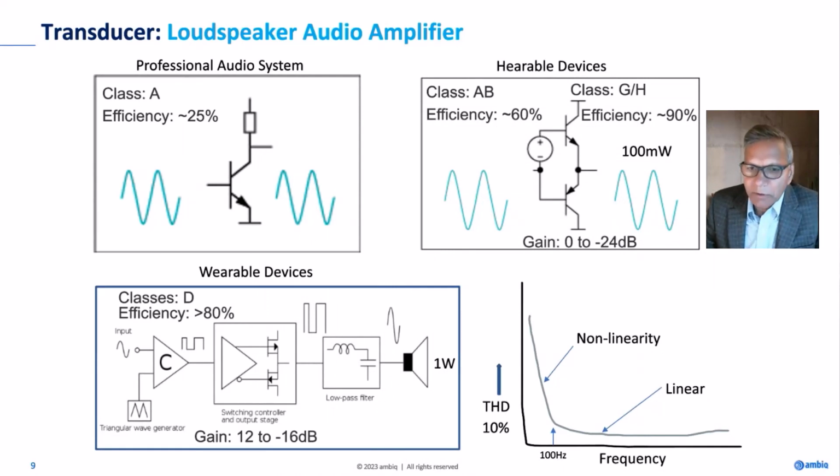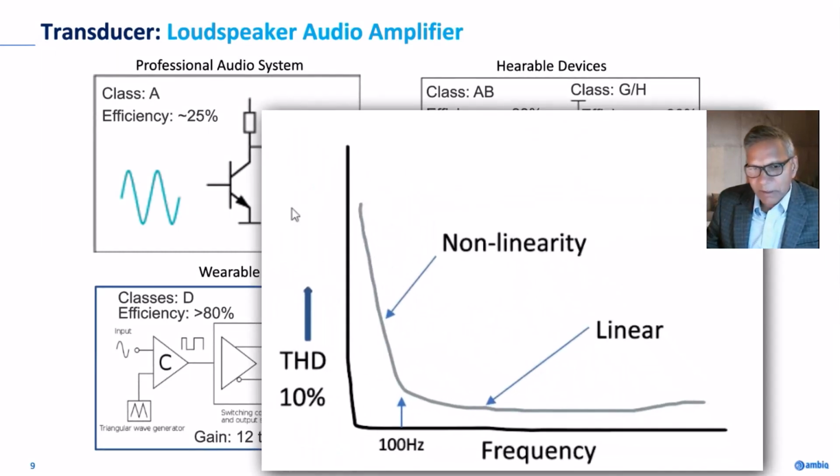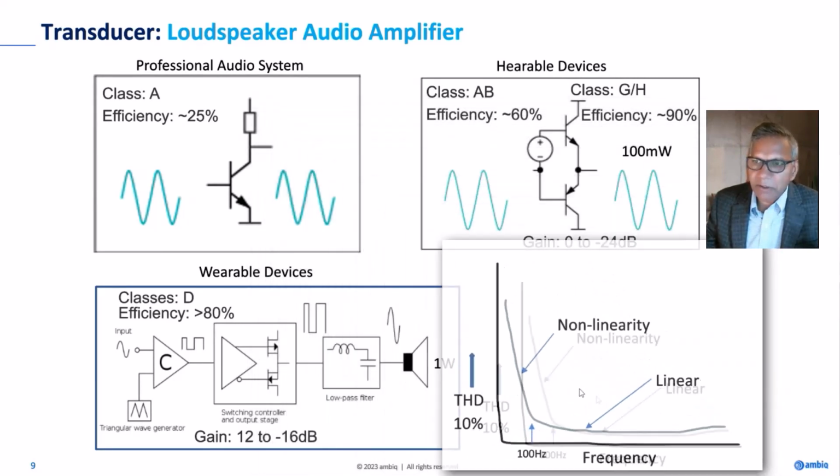This curve will come in handy when you are tuning the system: how I should apply a DRC, and what kind of high pass I need to use. So this is extremely important to understand, and based on my own experience, you want to measure this when you are using pure acoustics, not including signal processing. This will give you an indication of how well your acoustics is designed.